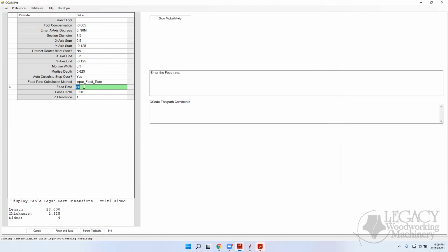Now, when it comes to the drilling toolpath, I'm not sure. I haven't used that yet, so I don't know. We'd have to check with Mike, find out if it's got peck drilling. But this one doesn't peck drill. It plunges and just cuts.